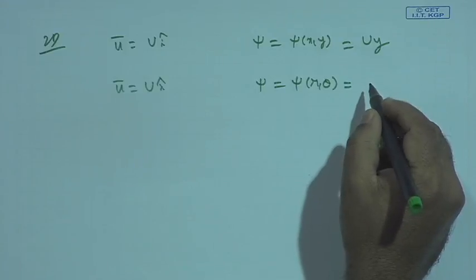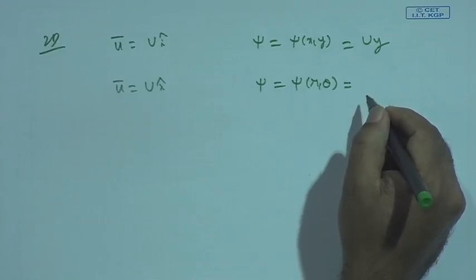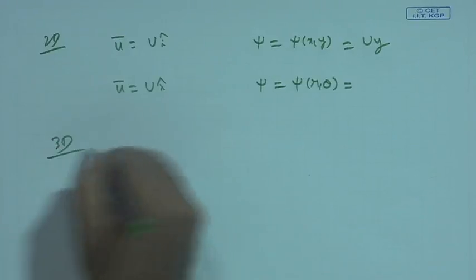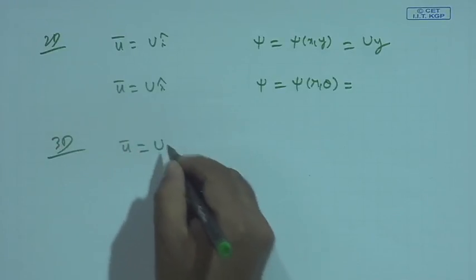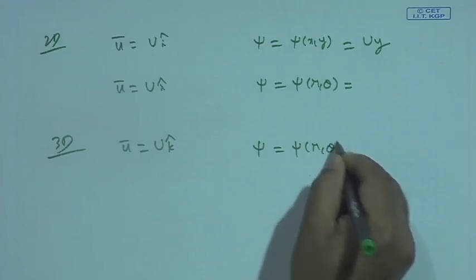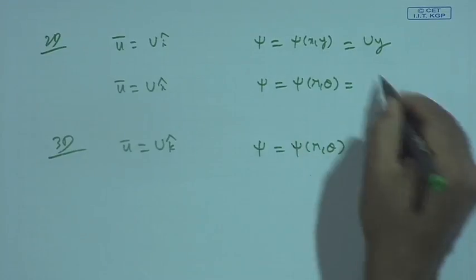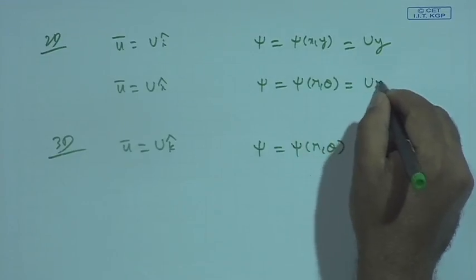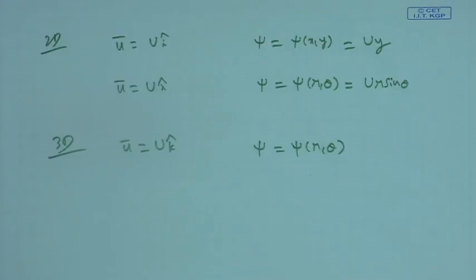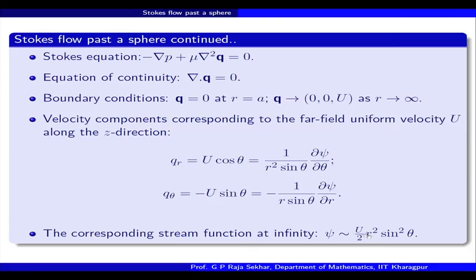Similarly, using the Stokes stream function, if u is u k, what will be psi of r theta? Since we have already discussed this, it should be a good exercise for you. Once you do it, you will get the corresponding stream function. So this is the far field for us in terms of the stream function.